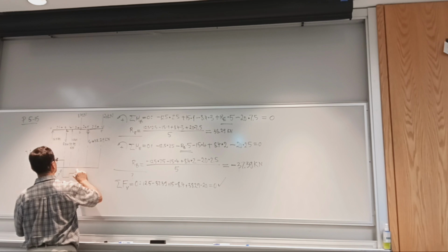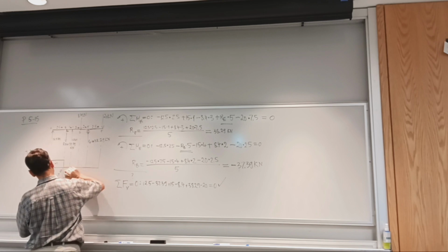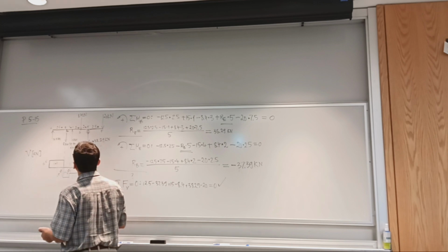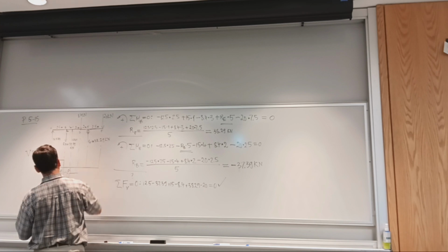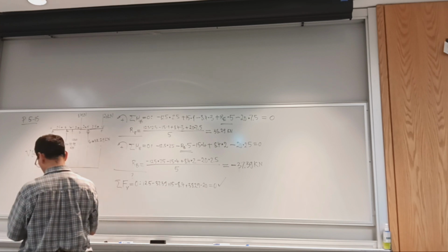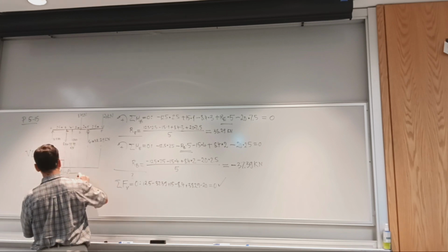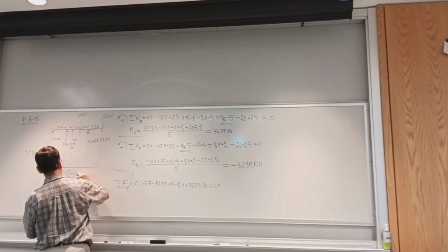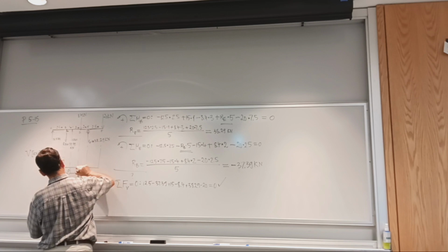And it stays unchanged. So this piece, again in the negative range, will be negative 9.89 kilonewtons. And nothing changes up until point D, where I have a drop by 8.4. So negative 9.89 minus 8.4 is negative 18.29, and it stays the same. So this is negative 18.29.